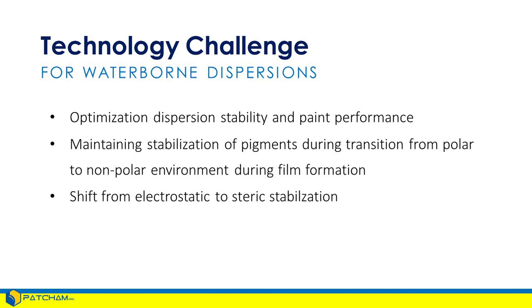These are very important facts to keep in mind, because this is very much ignored in our industry: the stabilization of the pigment during the transition of the paint after it's been applied from waterborne to non-waterborne. That means it's going from a polar system to a non-polar system during drying and film formation, because the water is leaving. And when a certain amount of that water leaves, it's no longer a waterborne environment. Now it's an organic environment.